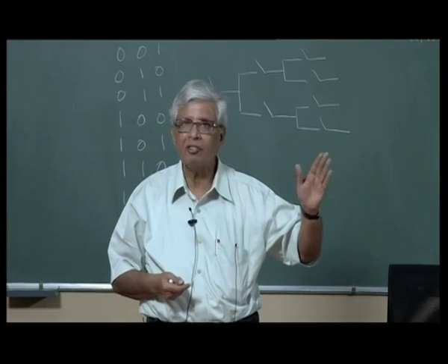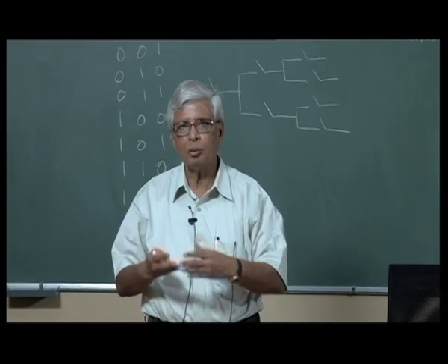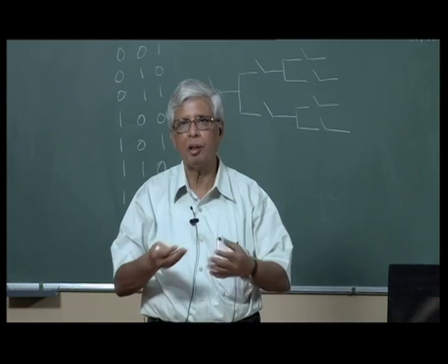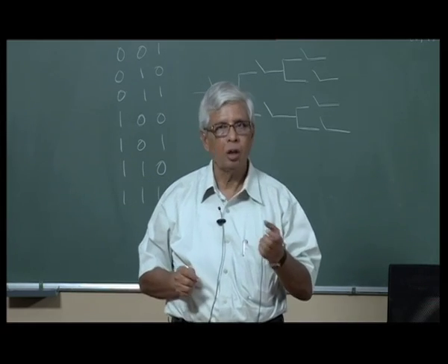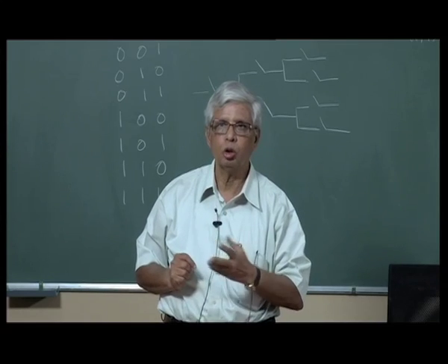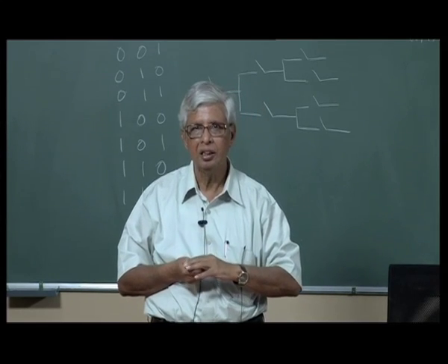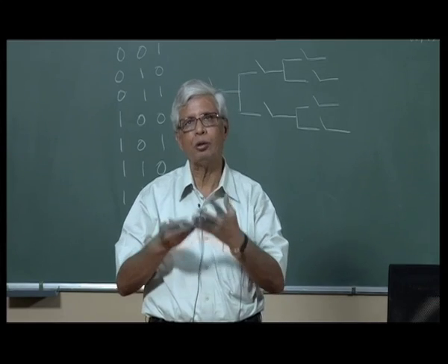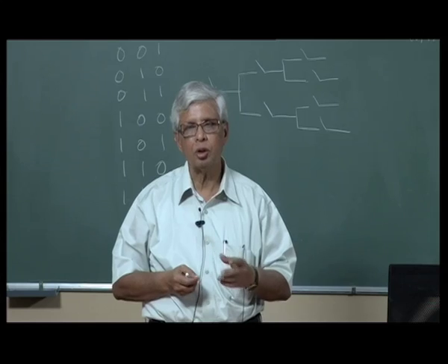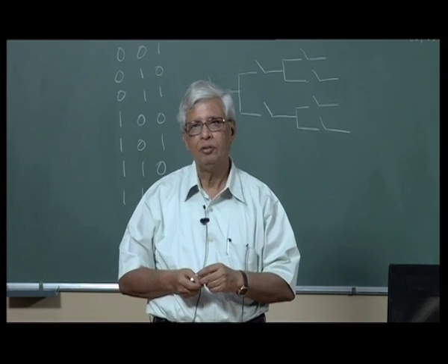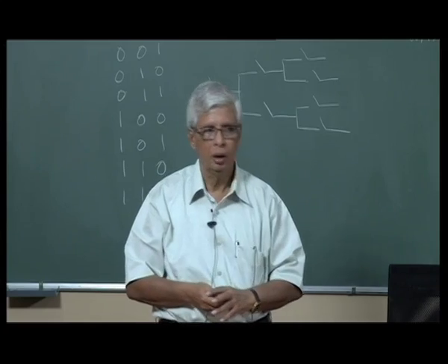I will not have a negative value there. So there is nothing like a negative number, positive number. I am going to count the number of people. So that is unsigned numbers. So all the 8 bits I can use, 0 to 255. Or if there is only a capacity of 100, I need a maximum of 127 because 100 is not a 2's power. So 0 to 127, which is 7 bits. Then I will have a 7-bit counter.